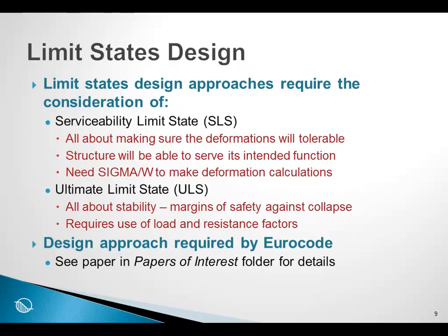For those of you who are working in the context of the Eurocode and are required to work in terms of limit states design, you may be interested in a document that we have produced, and the title is Using GeoStudio in the Context of the Eurocode. This document is in the Papers of Interest folder and is there for your convenience if you need to work in this context. But the point here is that to work in the context of a limit states design, we must use sigma W type of analyses.